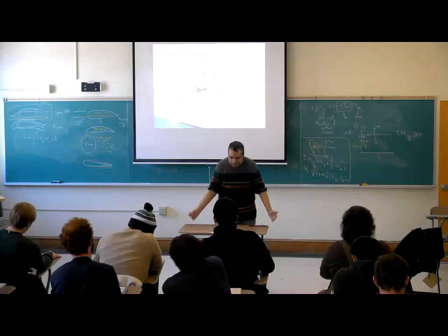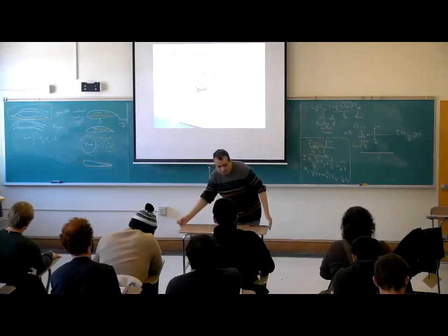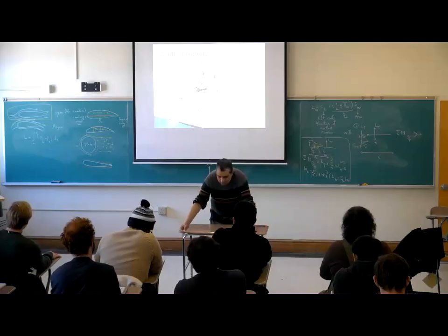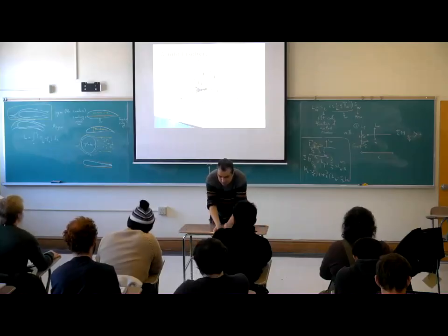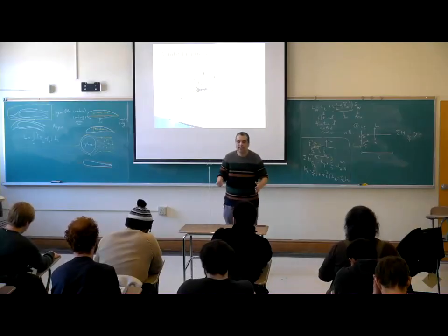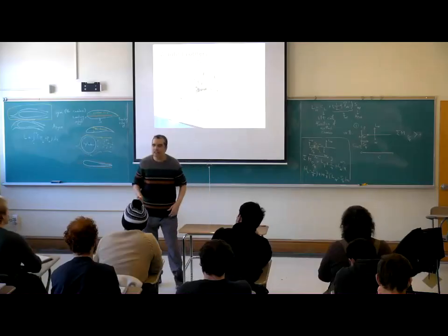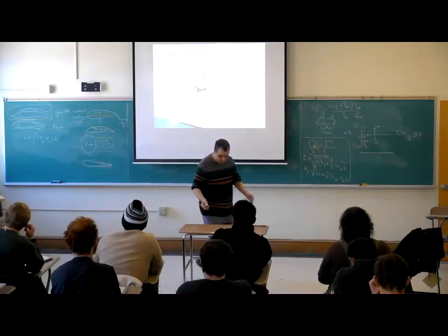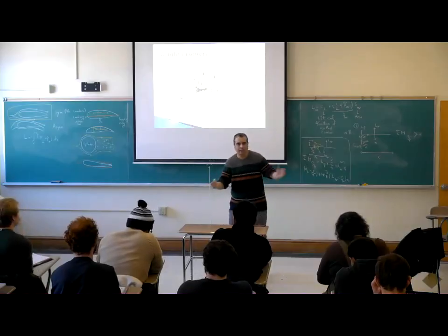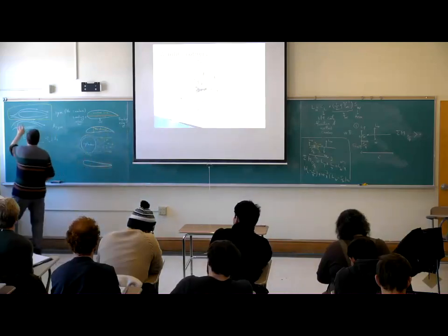I see it is symmetric, so it takes me the same time to reach here and the same time to reach here. If I don't separate, I go back and continue this way. So this geometry doesn't create any lift, because the flow is divided equally on the bottom and top side. But take a look at this one.